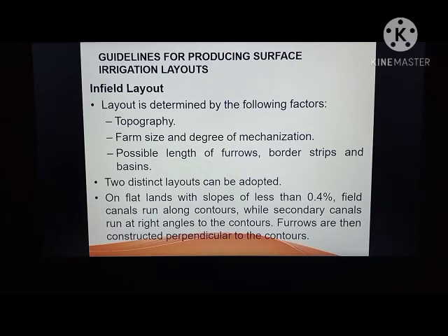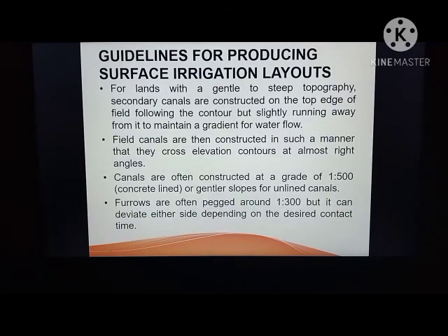On flat land with a slope of less than 0.4%, field canals run along contours, while secondary canals run at right angles to the contours. Furrows are often constructed perpendicular to the contours.